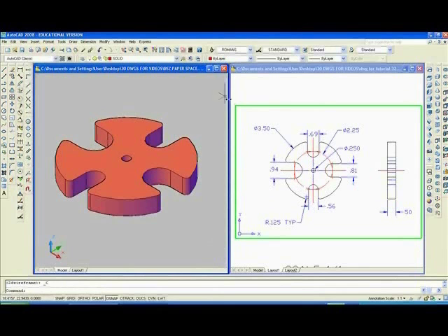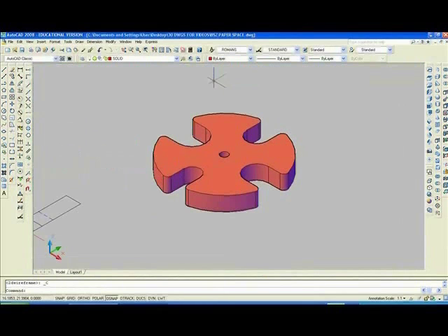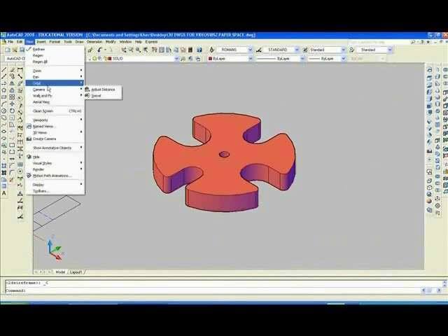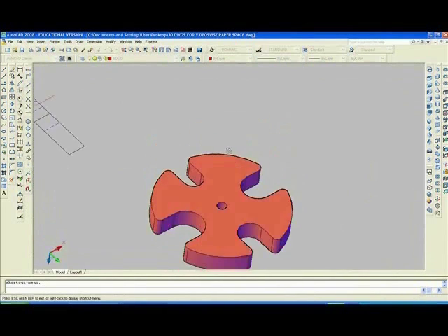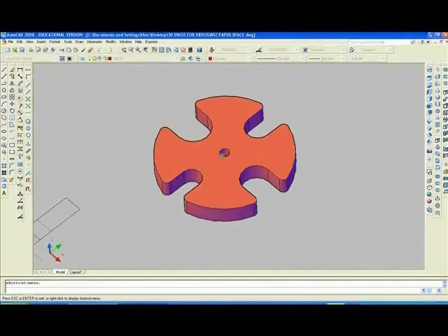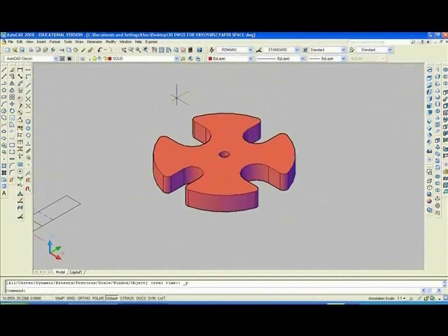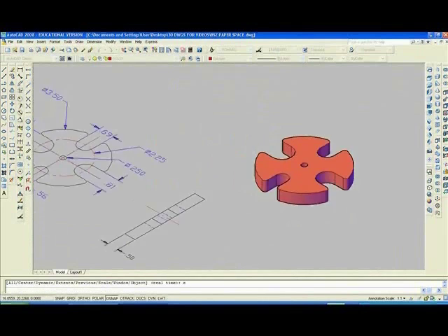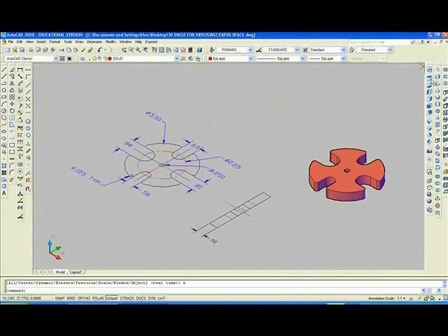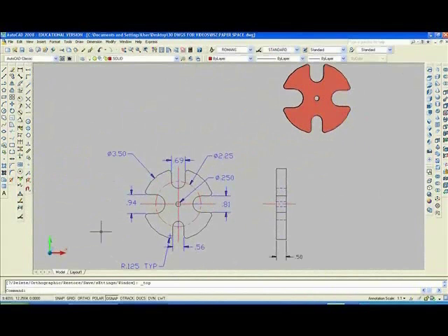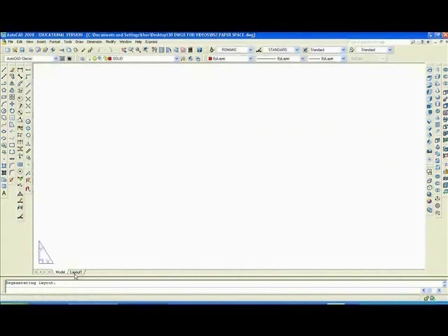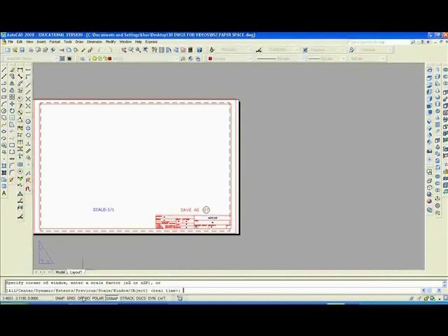Looks okay. So what I'm going to do is enlarge the drawing, and just for fun, so you don't forget, you can go to orbit, continuous orbit, and you can play with the thing one way or another. I'll zoom previous, zoom, Z, enter, E, enter, extents, move into top view, move into layout or paper space, Z, enter, E, enter.